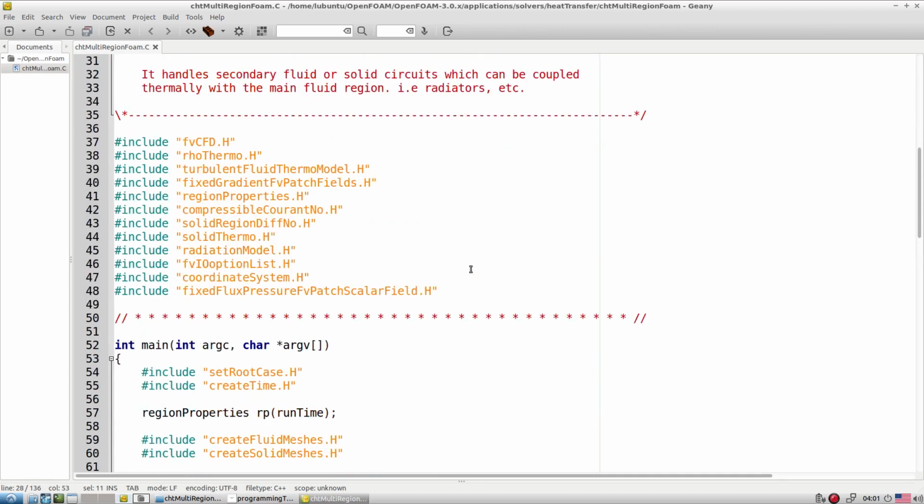So if you look at it, it is more like developed for compressible class of fluids. So we want to redefine a new solver that will allow us to simulate on an incompressible domain, and we don't want to go towards turbulence, so an incompressible laminar domain. That means we have to adapt the flow solver from the incompressible side, that is the transient incompressible solver for laminar application. It's icoFoam, so we adapt from icoFoam, and from icoFoam to PISO or PIMPLE, it's very easy. So let's start the development of an entirely new solver.